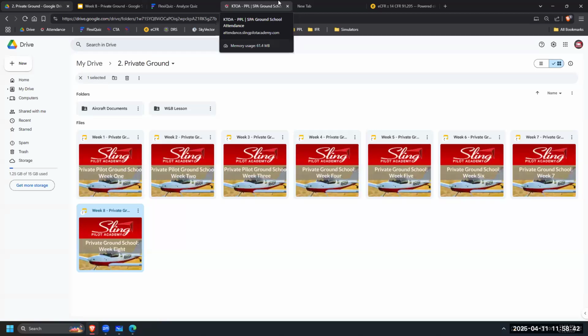Okay. So master off, what's next? Ignition lanes on, remain on. It's gonna stay on. If you turn this one off, the engine is gone. You have a bigger problem. Okay, what's next? Electrical switches off. Anything else? Extinguisher use if possible. That should solve the problem, I think, hopefully.